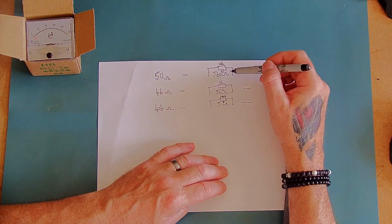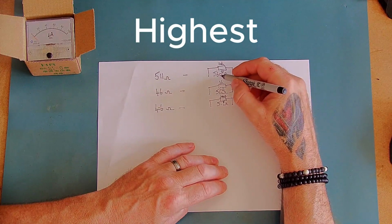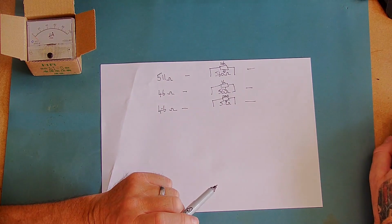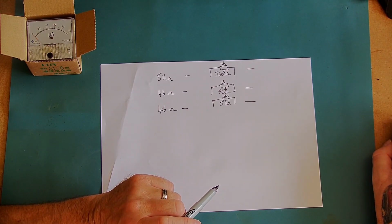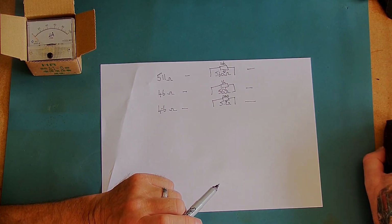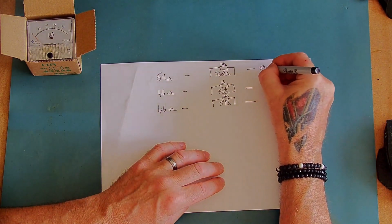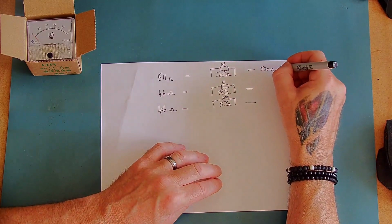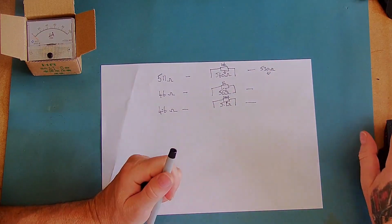If we do the calculations on those, it's basically just two resistors in parallel, which will give us the highest value, and then obviously we can go lower than that. So a 560 ohm with a 10k across it, let's go to the calculator, comes out as around 530 ohms, which is the max, and then we can go down from there.